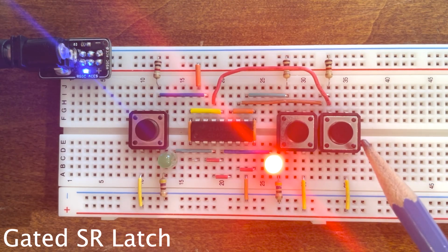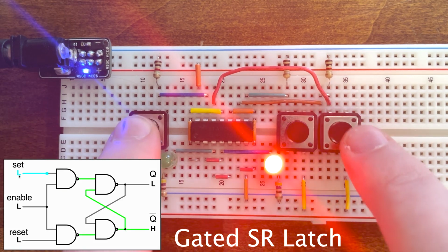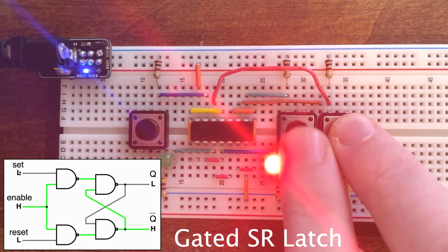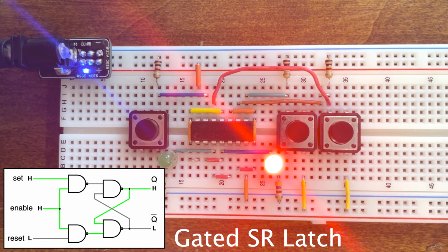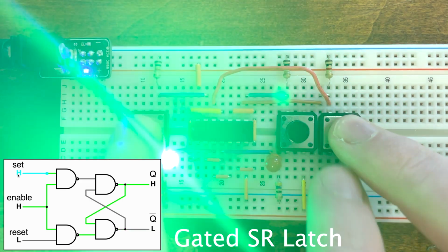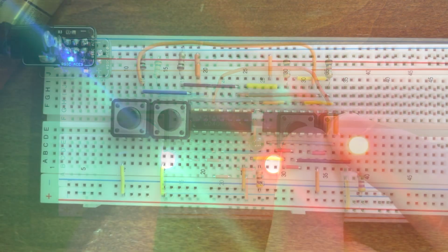The gated SR latch adds an enable pin using two more NAND gates, which disallows the latch from letting any data through when low, but allows data through when high. This is an improved design from the SR latch, but still presents a problem. This latch can be in illegal states. For example, if both set and reset are set high, it presents an unstable state.